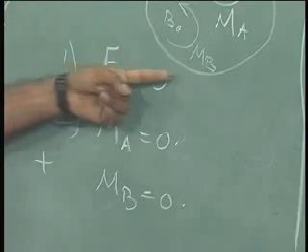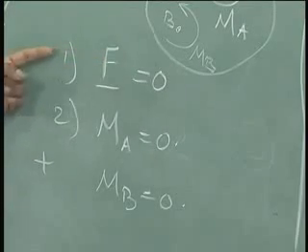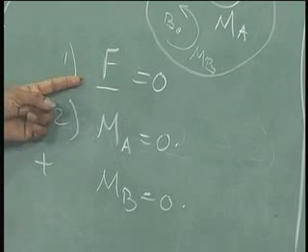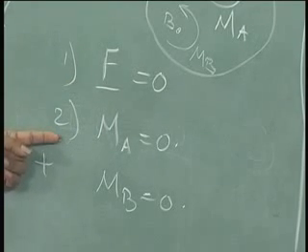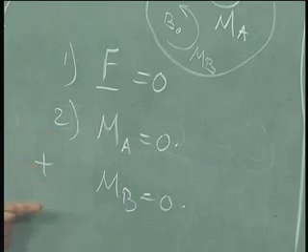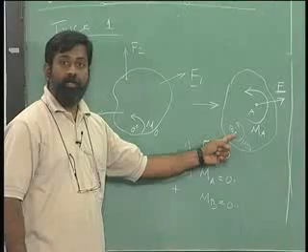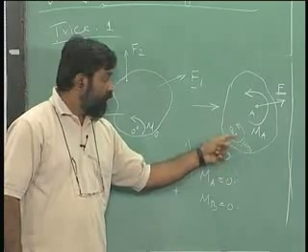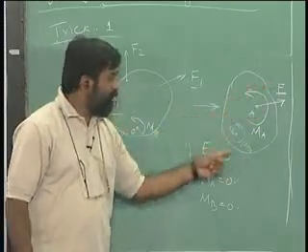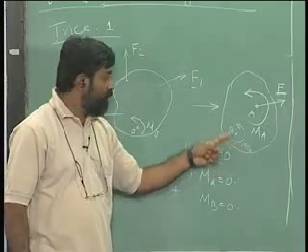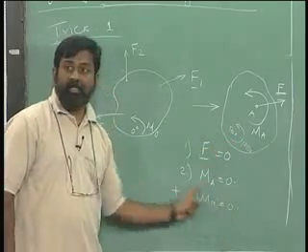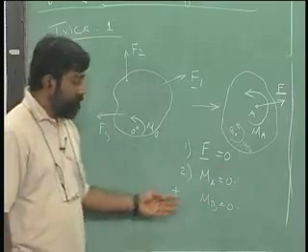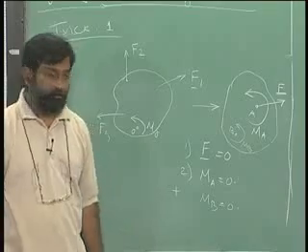Remember, there are two equations that I can find from here, which is x component and y component of resultant force equal to 0, MA equal to 0. Supposing I say, okay, I am going to take another point here, I know that this point is also stationary and therefore the resultant force is going to be the same, but moment will be different, MB, and can I add that and say I have the fourth equation? Can I do this? That is the question.